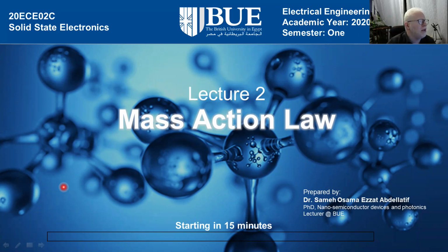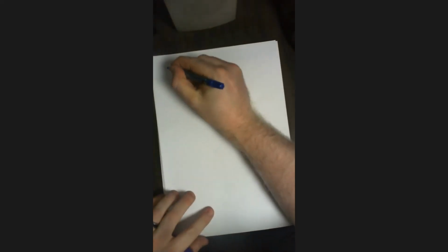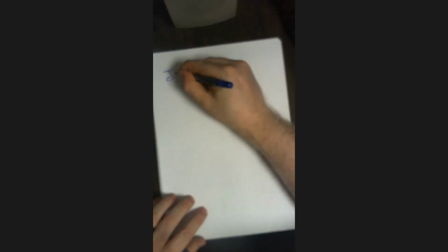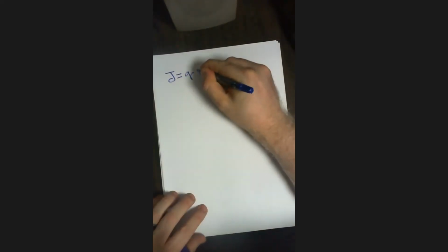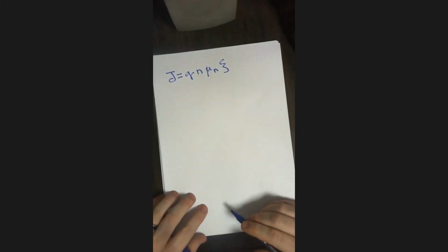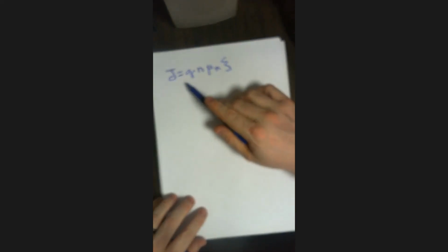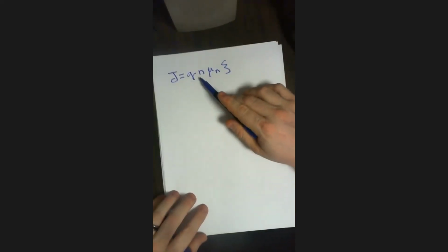Let me now use for a while my simple whiteboard. So here is my whiteboard. If you remember, we have the relation saying that J, which is the current density, equals q n mu n times the electric field. And here, J is the current density given in ampere per meter square. Q is the unit charge of an electron, which is 1.6 times 10 power negative 19. N is the number of electrons.